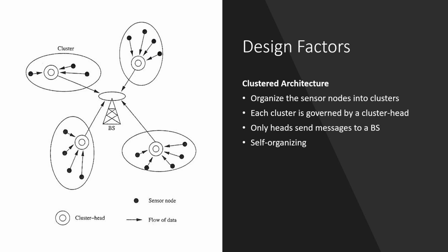The base station can send data to any cluster easily because of high signal power, but if all the nodes in all the clusters send data directly to the base station, they will decrease their lifetime significantly, which is why they send data only to the cluster head, and only the cluster head has to be sacrificed, so that the data of the entire cluster can be sent to the base station, okay?